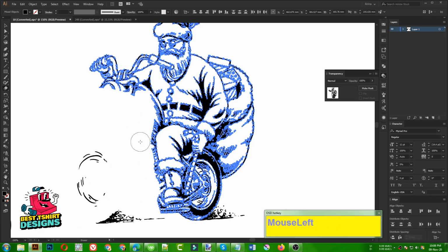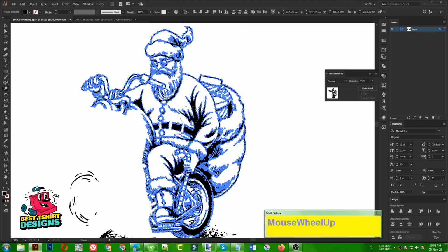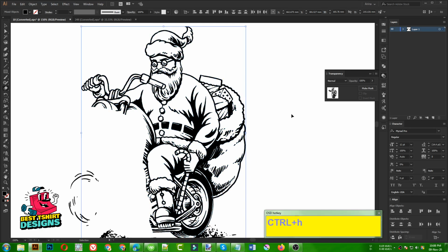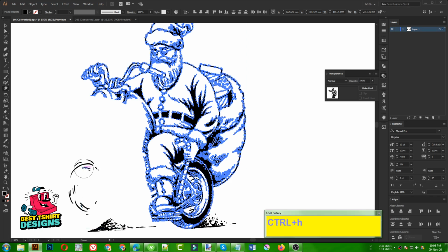As you can see, these small anchor points are causing some trouble for us, because this is hard to see. So I am pressing Ctrl H to hide those. You can see my graphic is not selected. If I delete anything, it will be deleted, but that is not showing. And if I press Ctrl H again, it will be back.